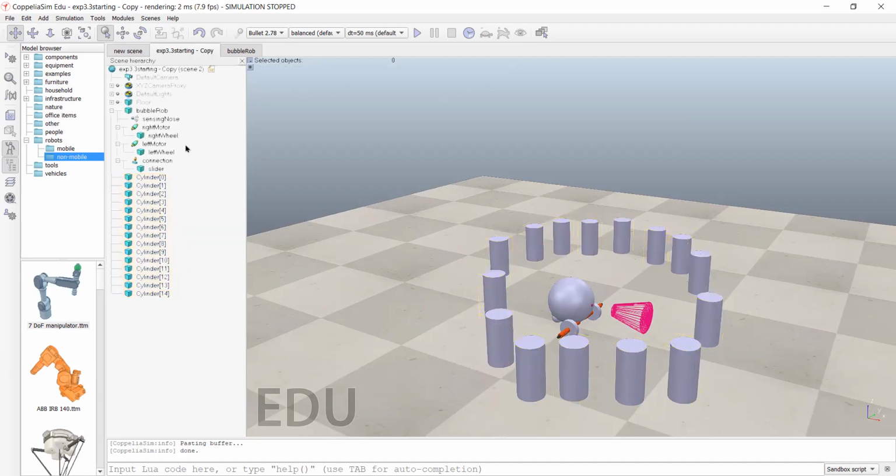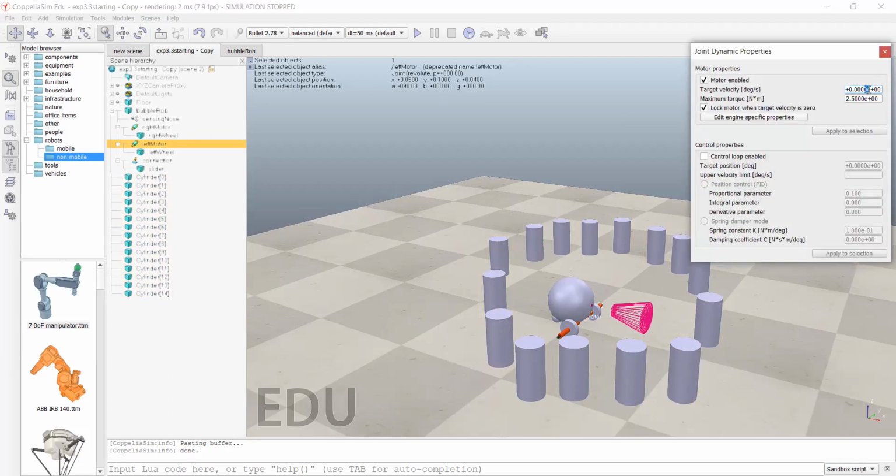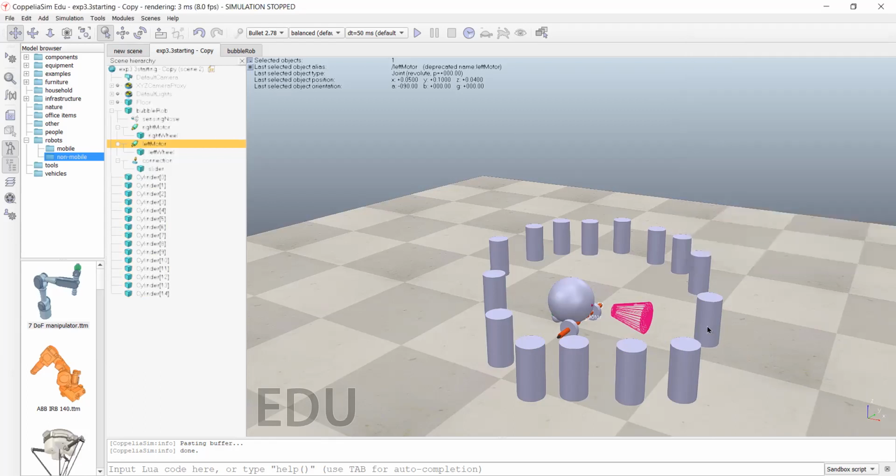Now here in one motor the velocity has already been given. So we need to give velocity to another motor. We know the procedure how to give velocity. For that we need to click this symbol of left motor and go to show dynamic and give the velocity. Earlier I have taken 100 velocity, so I am taking 100. If you take 200 velocity, then you have to take the same velocity. Cross this and now we can check whether it is working or not.